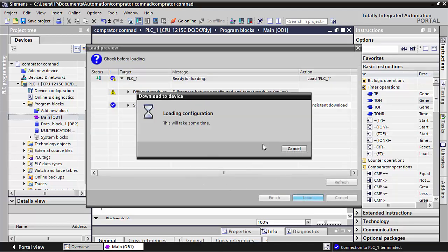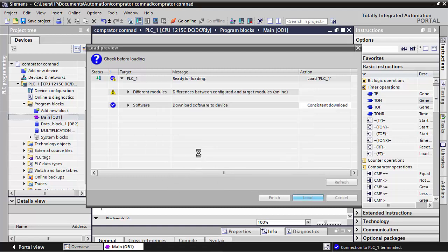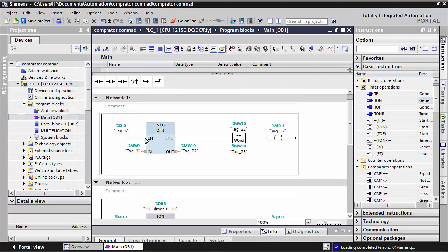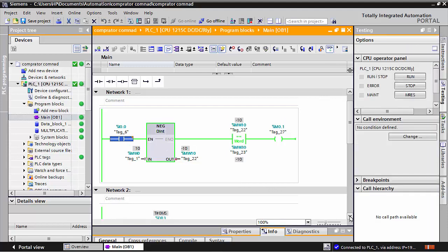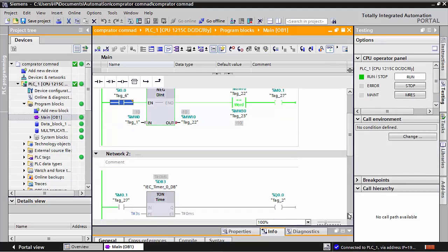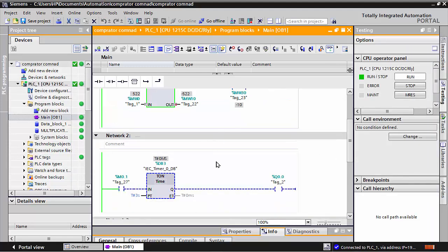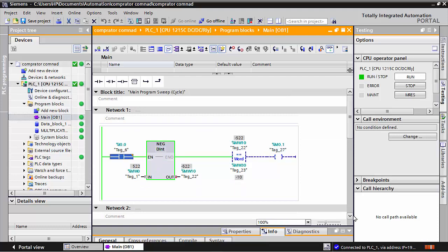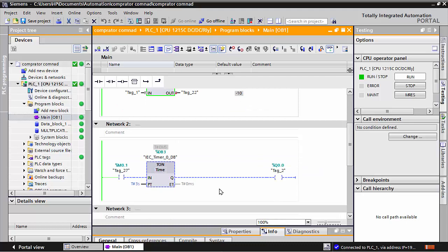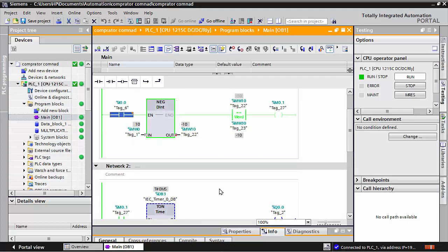It all depends on your logic and how you make the logic for any machine. When you start from there, data 0.0, see my coil M0.1 is on. Now it's off. Which data did we fix wrong? This one. Some data we fixed wrong.